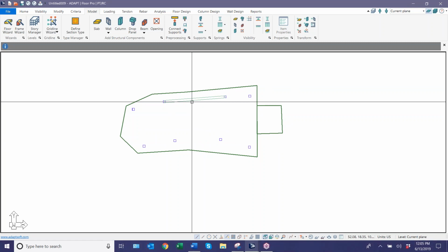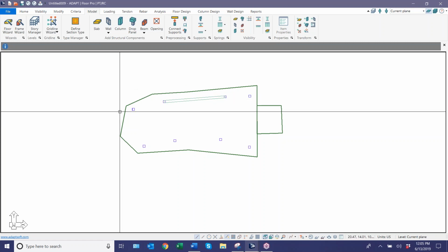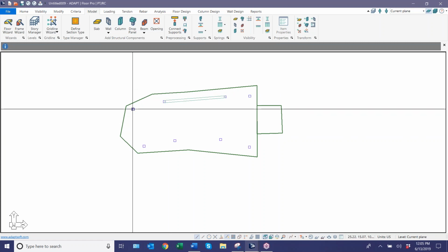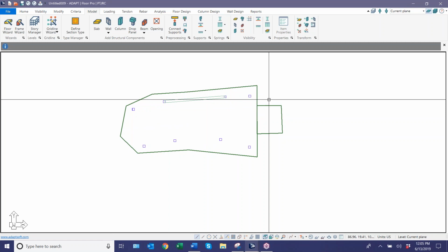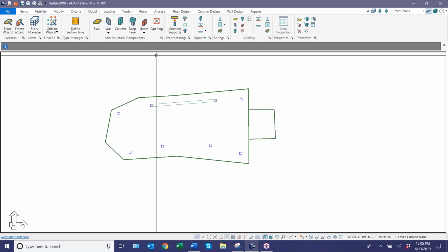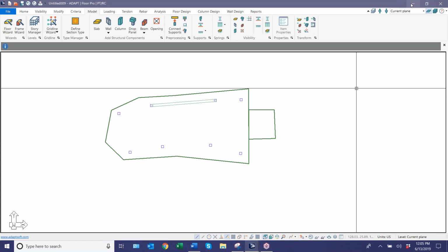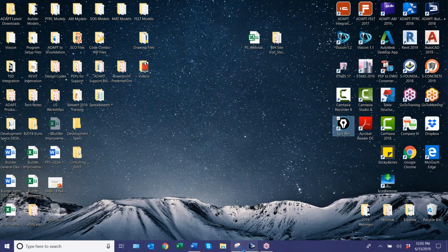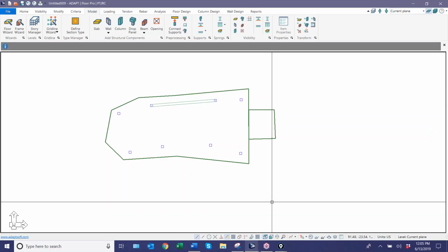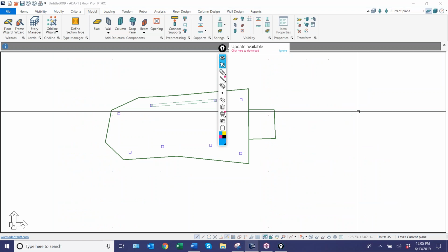And the purpose of this example is really meant to show how we handle the beam that's continuous, part of a continuous two-way slab strip, and how we handle this balcony. We're going to mainly use X direction support lines to process this. Let me just open up my marker tool here so we can use this to mark up the slab. I'm going to save this file.